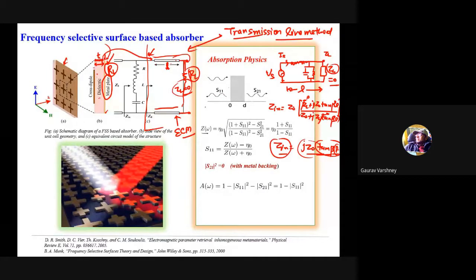Now this part is still remaining. This is the cross shaped resonator, already I told you. A resonator means it provides minimum reflection over a certain frequency spectrum. And one more thing, if we are going through the concept of absorbing cells, then definitely this is blocking transmission in the same frequency range.